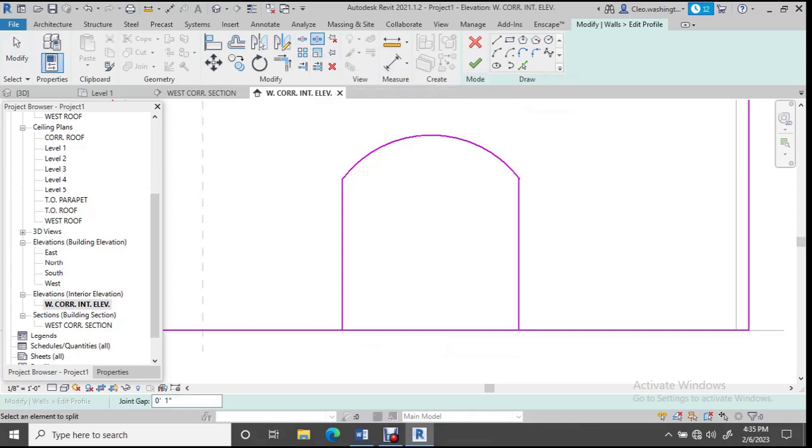Sometimes Revit will glitch if you go too fast for it. Or let's just try the other guy. This one is split element. So we click here, select that guy and delete it. Now we're going to trim and extend these two because they have to be closed loops. So TR, select here, here, here, here.